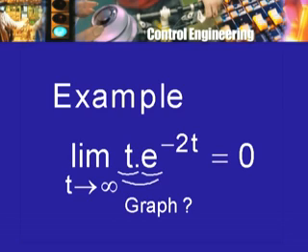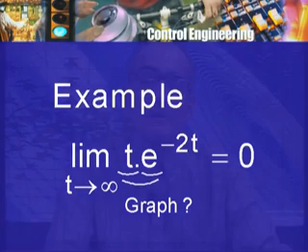However, as far as long term behavior is concerned, or the steady state behavior is concerned, this is no problem. The t is swamped over by the exponential decay, so it does not create any problems. Similarly, when we have oscillatory behavior, then the t will cause a problem if there is no exponential damping, but there is a problem already if there is no exponential damping, either oscillations or growing oscillations. So t will only make it worse. So this is not a terribly bad thing to worry about, a factor which is common to P(s) and D(s).